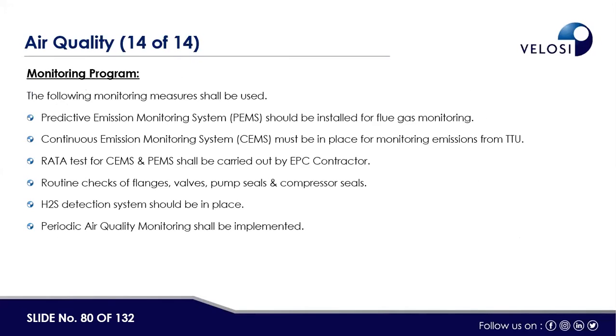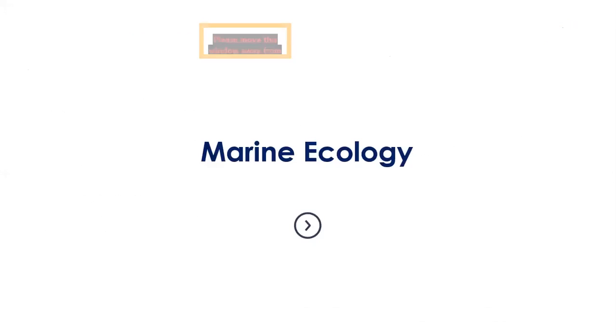Then we mention monitoring programs. The following monitoring measures shall be used. Predictive emission monitoring system should be installed. Continuous emission monitoring system must be in place. Data tests for CEMs and pumps shall be carried out by the EPC contractor. Routine checks of flanges, valves, pumps, seals, and compressor seals. Leak detection system should be in place. Periodic air quality monitoring shall be implemented. So these are the monitoring programs that we propose for this project.